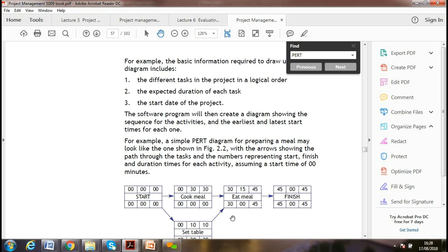That is called program evaluation review technique. We plan it, and we can review it: do we really finish in 45 minutes? If we do not finish in 45 minutes, where did we spend the time? So for each step we can evaluate the time and the cost within a project, like the digging cost, the surveyor cost, the finishing cost, and the total overall up to the handover.